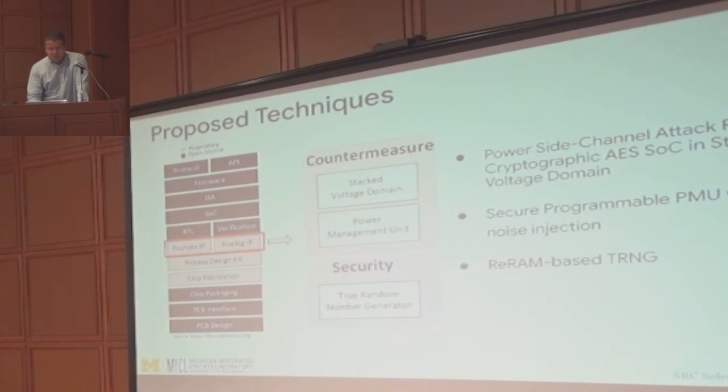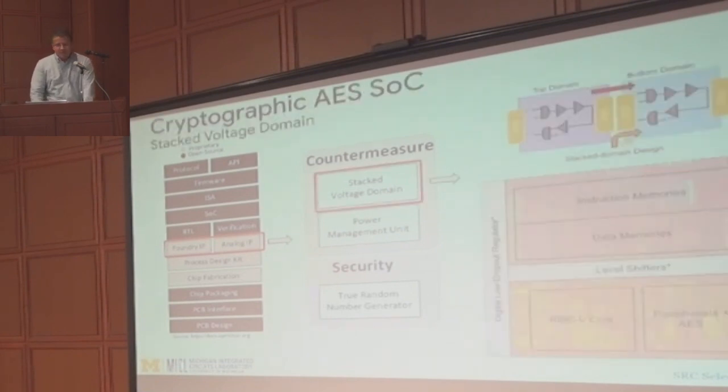We're proposing a couple of countermeasures to mitigate side channel attacks, such as voltage domain stacking, which I believe could minimize the power signatures of the AES accelerator. We're also developing a new secure programmable PMU, which underscores the flexibility and broad applicability of the OpenFASoC approach. The PMU is using an OpenFASoC generator approach, and we created security primitives such as ARM-based generators.